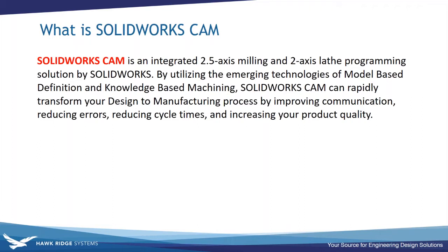You can teach that database how you like to machine things. You can set all those feeds and speeds and different machining parameters. The great thing about having it rules-based in the database is that everyone can program the same way across the board. You have people in the shop during the day and in the evening all using the same database, and everything is getting machined the same way.